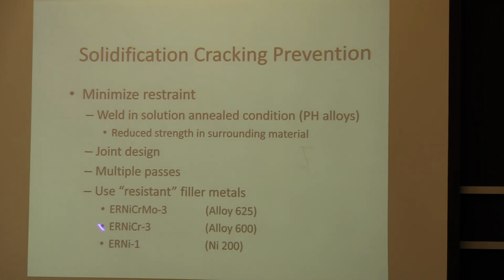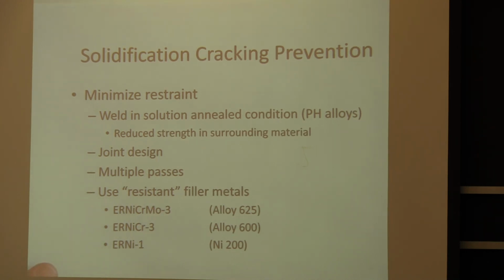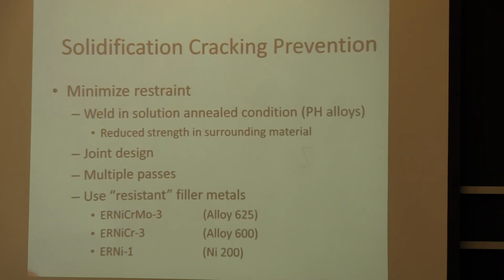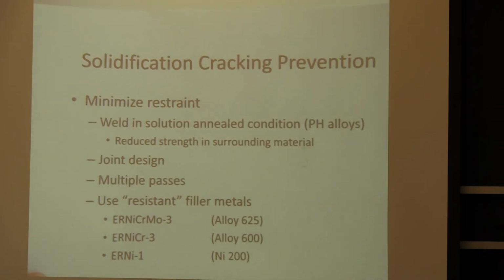But some of these alloys here are actually solid solution strengthened alloys, and this is a pure nickel alloy. You get less of that strengthening and hardening going on in the weld, which leads to lower restraint and less solidification cracking susceptibility.